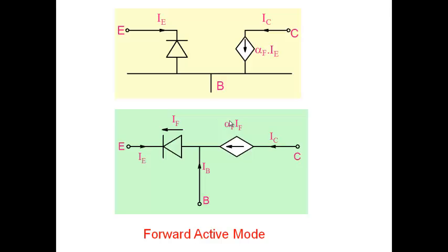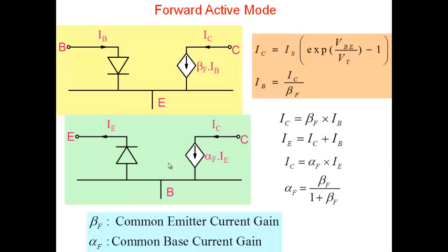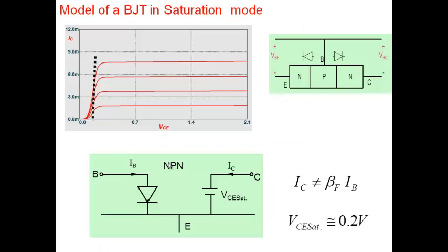When you forward bias the base emitter junction, there is this green current IN and there is this IP here. A part of this current flows across the collector base junction. Note that this current keeps on flowing in, and this is denoted in this model. This IN plus IP is the IF here, and IN that you see here is this current. Okay, so a part of this current flowing across this junction, the green one, gets coupled across the collector base junction. That's the normal transistor action.